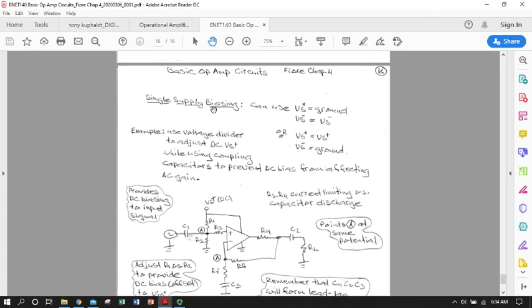So once we put our feedback network on, the only time we even thought about supply voltage was when we had a large value, large ohm load resistor, and we were putting a lot of current out, especially with our voltage to current converters, and we wanted to make sure that we weren't asking the output to give us a higher voltage to ground than the supply. So we just use this as a check of clipping.